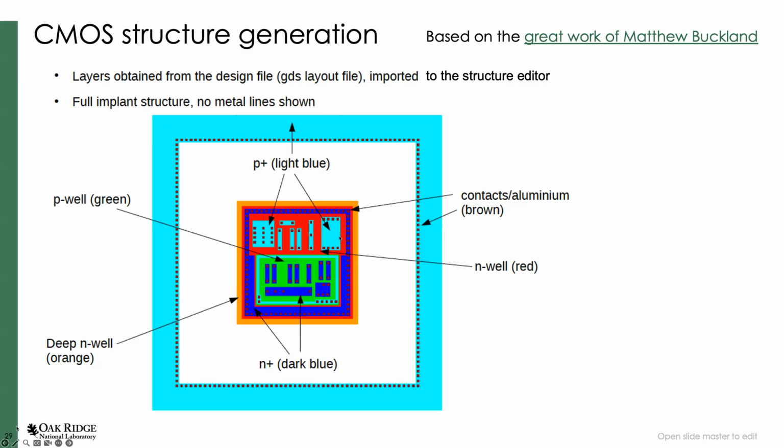So this is the structure that we wanted to design. We were interested in the breakdown. In that simulation, we were interested in locating where the breakdown occurred in the structure and seeing if there was any design help we could get from TCAD into avoiding that, or making the breakdown go a bit higher so we can bias the structure more. So we got the GDS file from the designer. The designer could directly make his design and give it to us, and then we could run it through the process simulation or through a device generation script, driving things directly from the GDS.